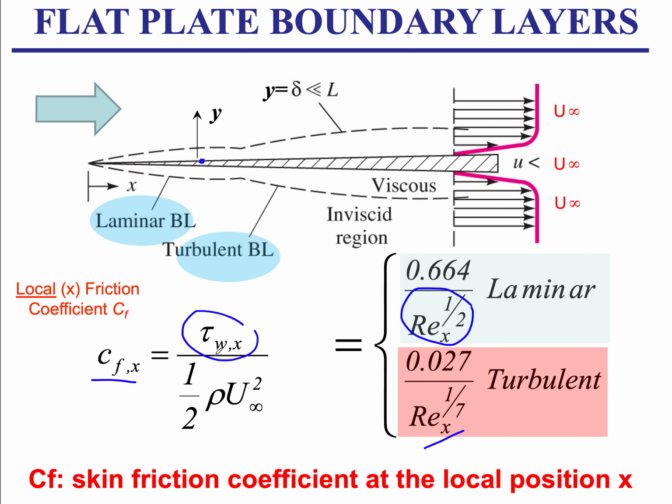So now I have found the shear stress, and we normalize the wall shear stress to get the skin friction by the dynamic head, 1/2 rho u infinity squared, and the u infinity is the incoming flow velocity, and this actually should be rho infinity, so it's the fluid density far away from the flat plate. So it doesn't include the effect of the flat plate. If there's an increase in temperature or compressibility or anything, we're dealing with incompressible flows. But just to say, it's a convention to stick rho infinity. That means it's far away.